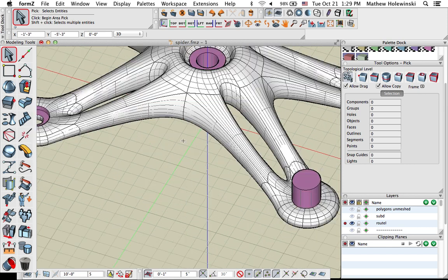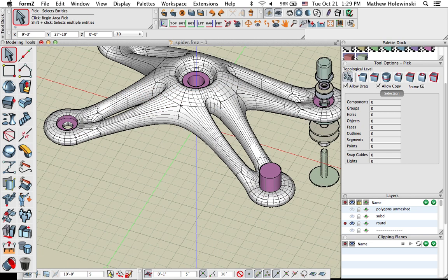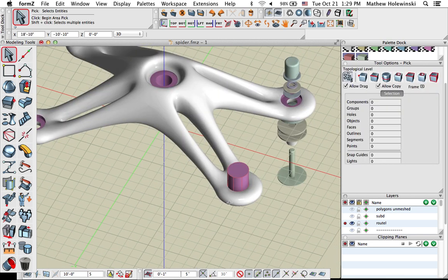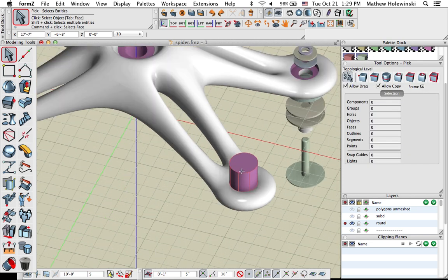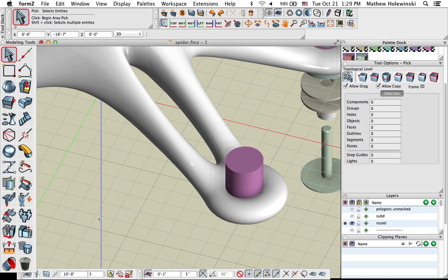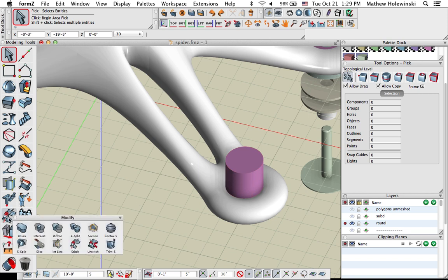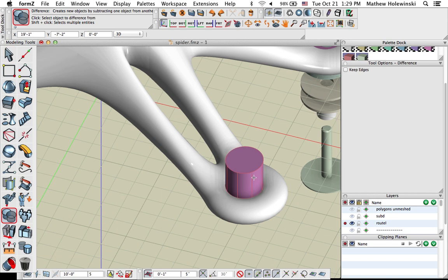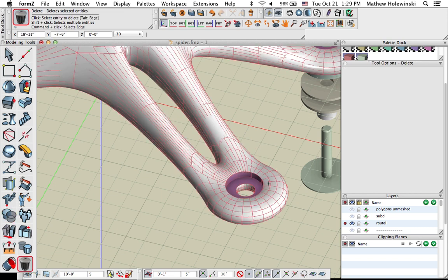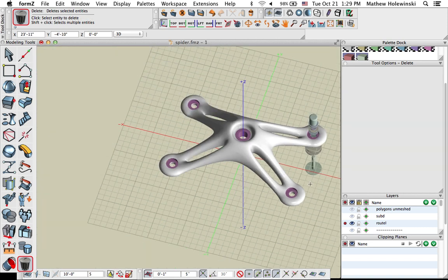And so in shaded work, you can see that better. But anyways, here you can see, I'll put this in shaded full mode. All I have to do is create a cylinder of the exact size for the counterbore hole. I do a Boolean difference and subtract that from my object. And then we end up with an actual machined feature there.